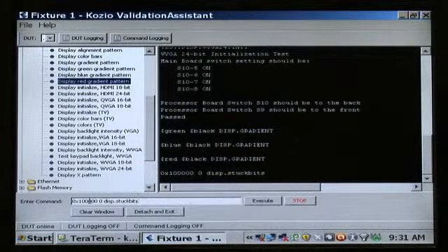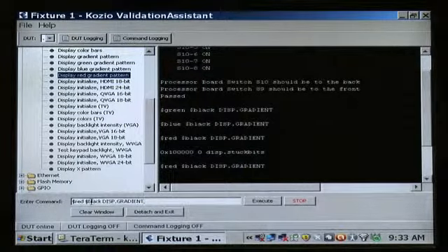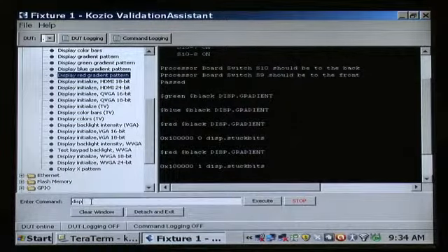First, we'll simulate the fourth bit being stuck low. Since the display output changes, we know the error is not this bit being stuck low, as we would have predicted. We'll now generate the gradient again and simulate the fourth bit being stuck high. Since the display did not change, we now know that bit 4 of the red byte is stuck at 1, and we can check for a loose connector or a bad solder joint. And we can even have some fun.